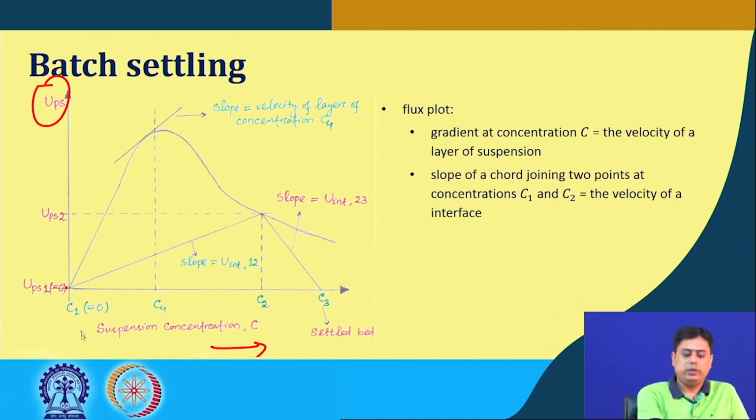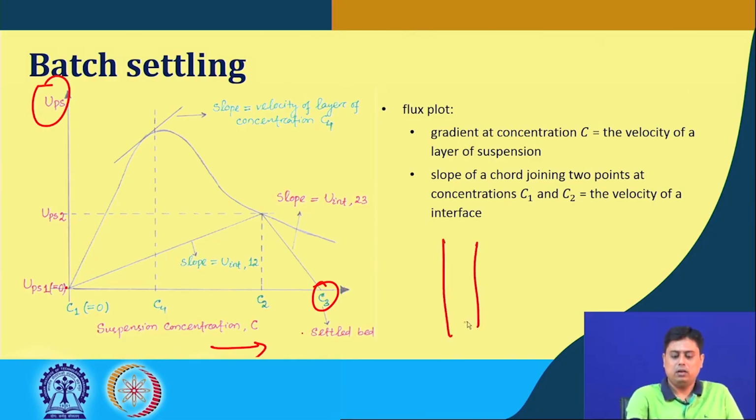As you increase the concentration, say at C3 all particles have settled and the sedimentation is complete. So, it is a settled bed with solid particles filled here and clear liquid at the top.